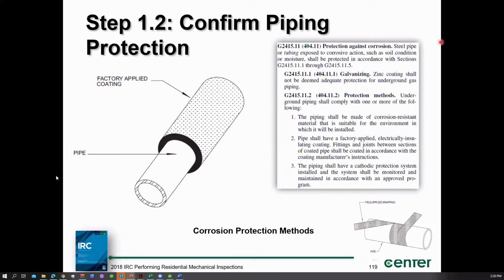This section is something you probably won't realize in residential construction: protection against corrosion, especially underground. In most residential occupancies, plastic piping methods are used all the time, and then we transition to a metal pipe using anodeless risers. However, if you have any type of metallic piping underground, you need to protect it by some corrosion resistant method.